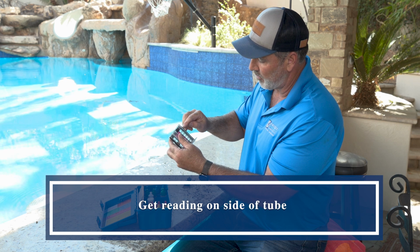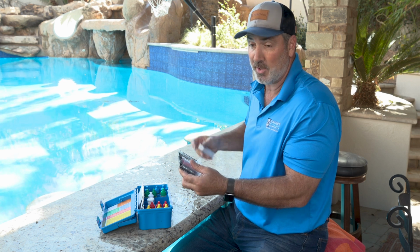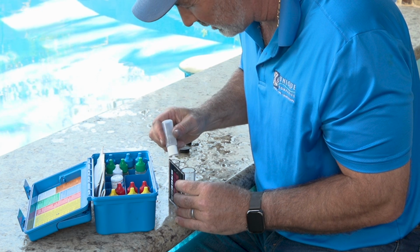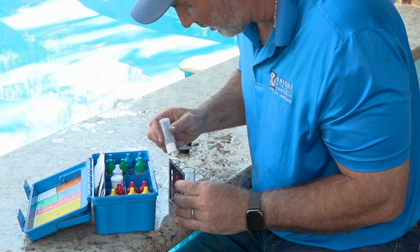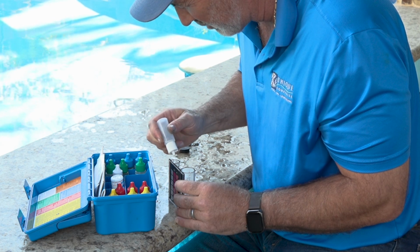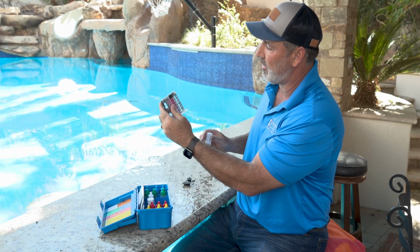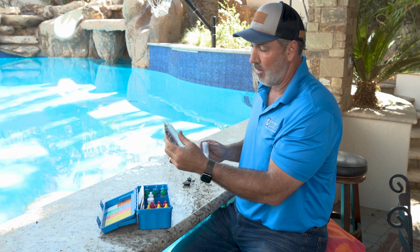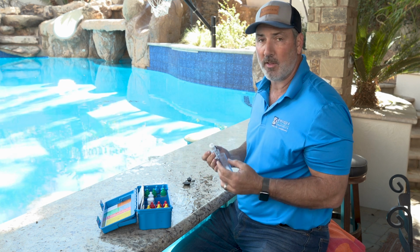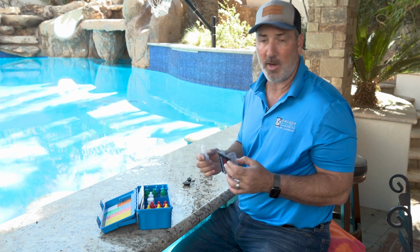The reading on the side is from 30 all the way up to 100. Once you get over 100, this doesn't even read it. It's because you shouldn't have cyanuric over 100. And slowly going to add it. Most of the time I can get mine all the way to the top. I can still see that black dot. And it's just starting to disappear now. So look at that. Mine's right around 35 parts per million of cyanuric acid. And that's ideal for the IntelliChem system that I have by Pentair. We want a cyanuric level between 20 parts per million and up to 50 parts per million max. And that keeps the free chlorine in the pool.